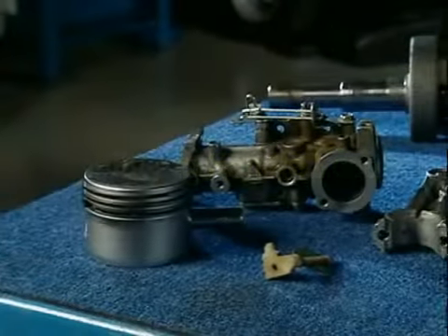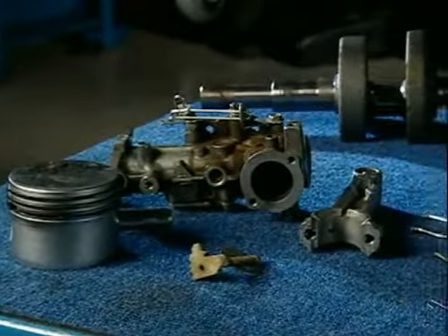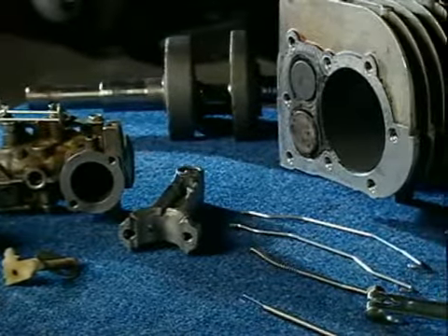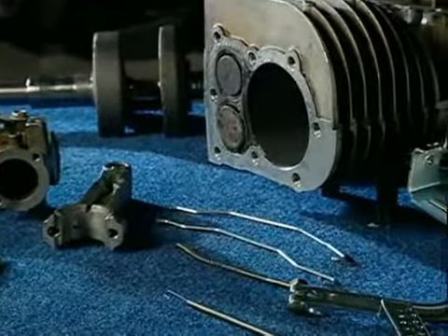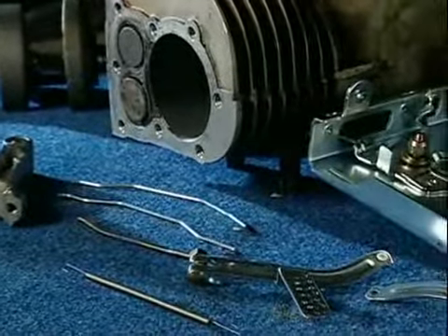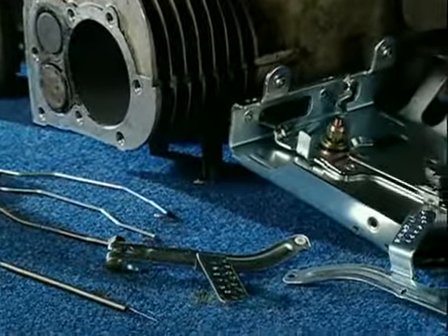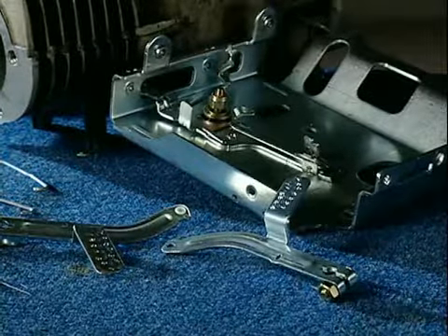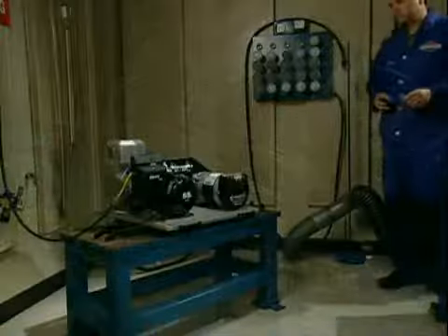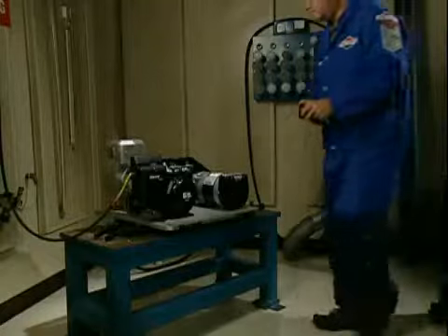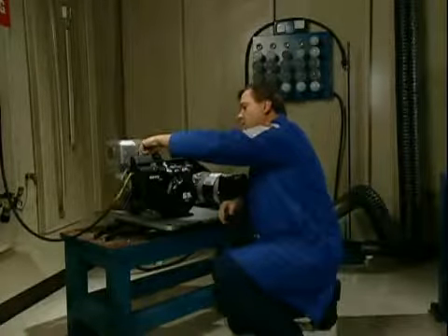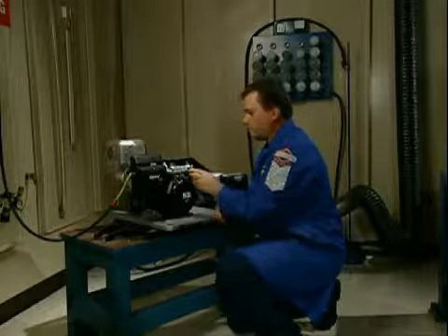Now let's spend a moment talking about an inability to handle load. This problem could be engine-related, such as carburetor adjustment, manifold air leaks, or worn or damaged compression components, or governor system related, such as worn, bent, or binding linkage or other components, bent or damaged speed control bracket, or a spring in resonance. This may be a tricky area to investigate, as a variety of areas may have to be explored, including whether an engine is suitable to power the equipment.